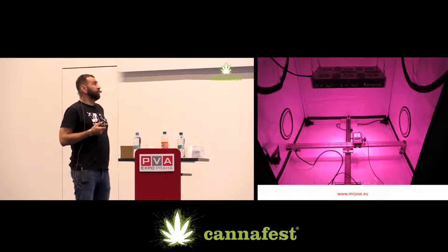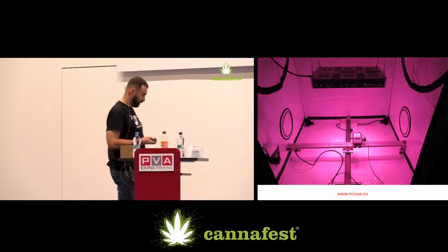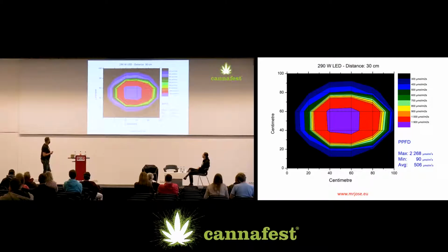And the manufacturer of this module promises 2000 micromole per square meter per second and more. So they were not lying, it was the truth. But you can't do it on such an area. This is at the distance of 30 centimeters. But you know, the field has corners, has angles. So this is 290 watt, 30 centimeters away. The minimum is 90. And that, of course, is not enough.